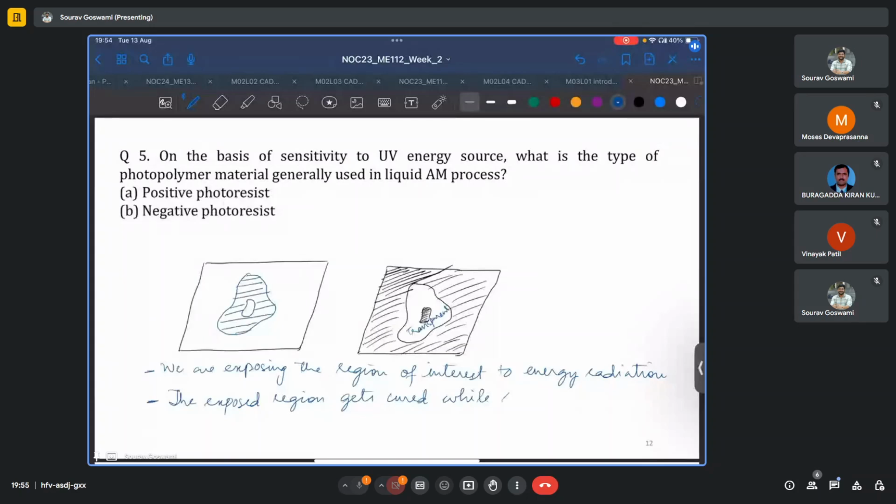The sixth question is asking us, during deposition of a material in a single layer, there are certain steps at which the process becomes unstable. Which of the following are such steps? Is the start of the print a step during which the deposition process is unstable? Yes, it is, because it is governed by inertia. You are suddenly extruding material from a condition of no extrusion, and thus it is expected that there will be either some over deposition or some under deposition.